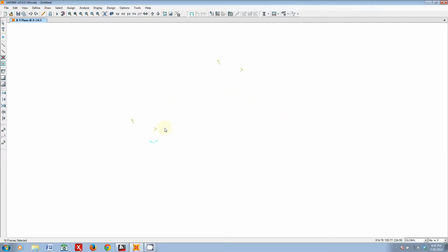Oh, well, they're not fully there. And this is actually a common problem that you'll probably encounter once you start importing and using perspectives in SAP. For some reason, SAP likes to default to certain funky perspectives where you can only see certain lines. So you can resolve this issue by clicking the perspective toggle, these little sunglasses. So when you click on that, bam! Alright, I can actually see my legs this time, and that's kind of what we'd expect.